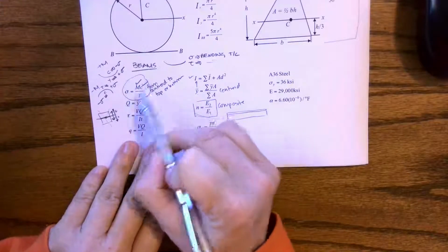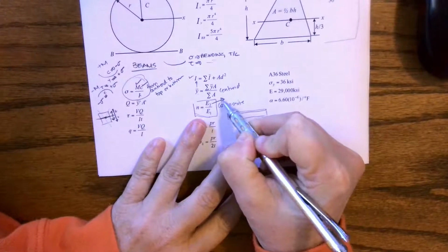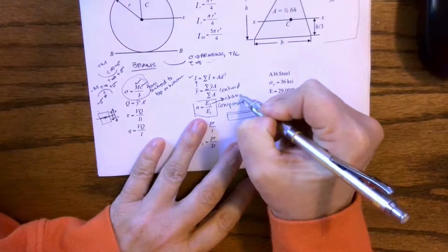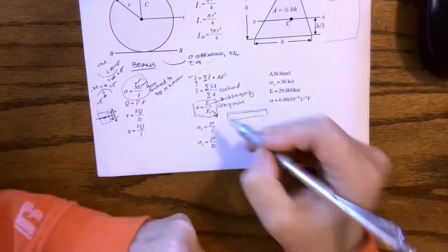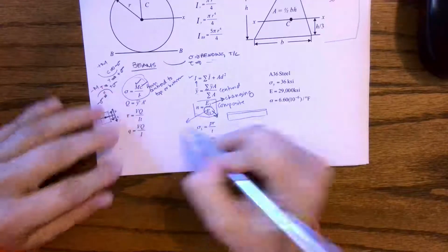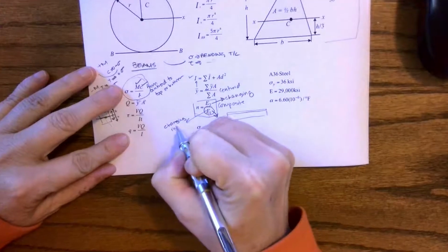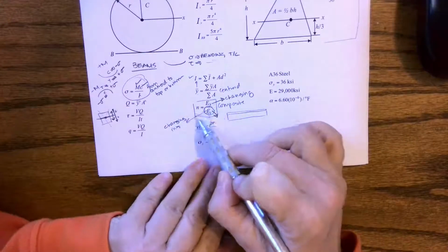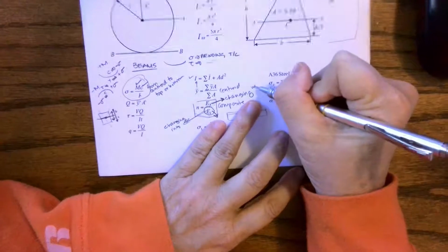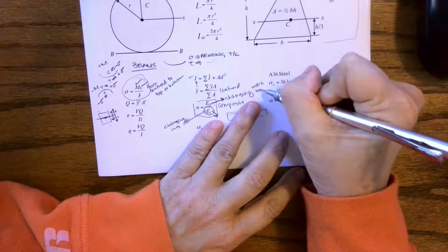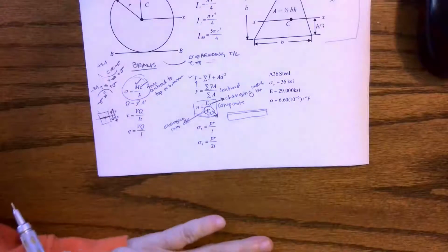This equation is only considering one material. The one on top is the one we're changing. The one on the bottom is like our common denominator; we're changing everything into a common denominator. If we're changing the top, our new width is b times that n. So it can either get bigger or smaller depending on this ratio.